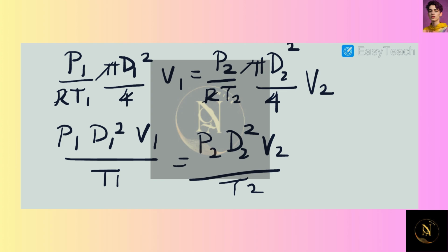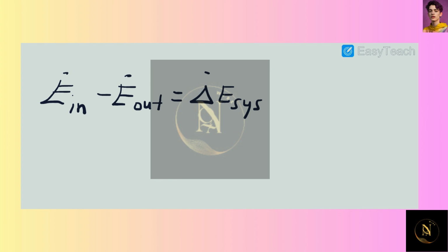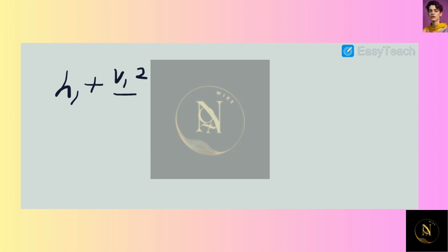Next, we're going to do our energy balance. Similar to our mass balance, the rate at which energy enters the system minus the rate at which it leaves the system is equal to the total change in energy rate of the system. As we assumed before, this is a steady state process, so this is going to be equal to 0. Therefore, E dot in is equal to E dot out. We can break this up into its constituents: E dot in is equal to H1 plus V1 squared over 2, so this is energy due to enthalpy and velocity that is coming in. We have that set equal to the energy leaving due to enthalpy and kinetic energy, but also the heat that is lost, so that's going to be Q out.